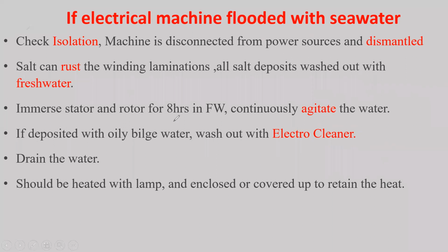You have to immerse it for 8 hours in the fresh water, continuously agitate the water, disturb the water continuously, and soak the stators and rotors. So take the fresh water and first clean the stator and rotor. It has to be free from the salt deposit because salt will rust the winding. If deposited with oily bilge water, wash out with electro cleaner.